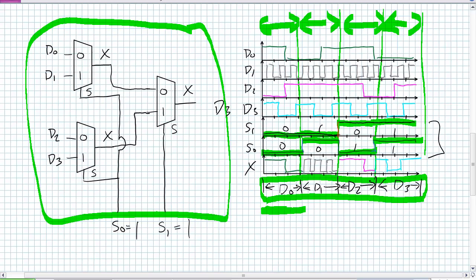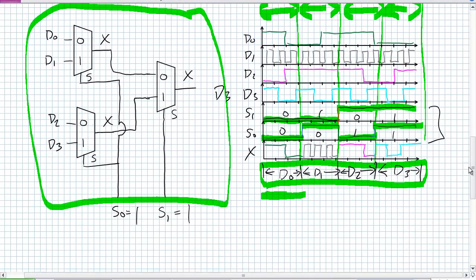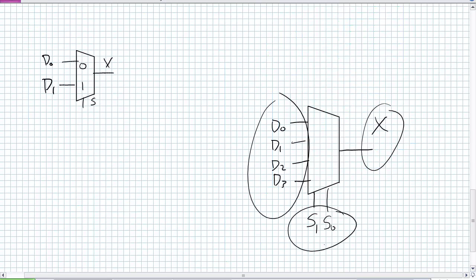The multiplexers and demultiplexers are an excellent way to introduce these behavioral descriptions. We've already gone over a data flow description of a 2-to-1 multiplexer. Let's go back to our definition of a 2-to-1 multiplexer. Let's see if we can find a blank spot. Okay, this one should be easy. What is the data flow or the SOP expression for that 2-to-1 multiplexer? We've got 3 inputs, D0, D1, and S. What I want X to be assigned, in this case, let's just use the SOP expression. When S is a 1, I want D1 through, or D0 when not S. That is an SOP expression.